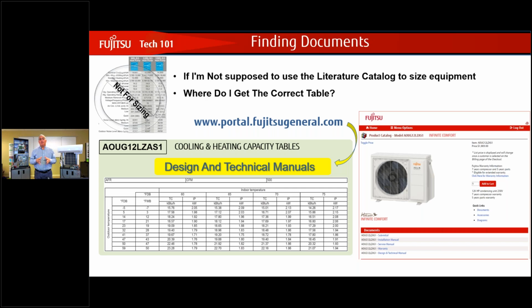All right, we don't have to do that in the world of Fujitsu. So when it comes to minimum line set, it's always horizontal, and it must be there. So we recommend in class all the time that if I'm putting the equipment in and it's going to be heating and cooling, obviously I've got to get the outdoor unit up above snow depth, right? Which could be 18 inches, 20 inches, 24 inches.